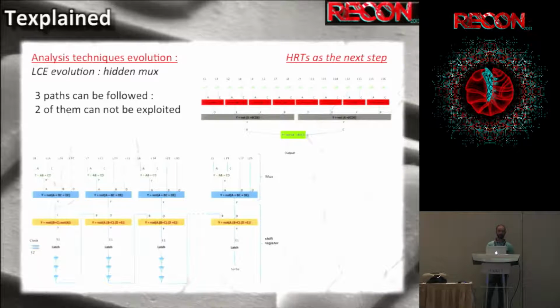The first pass was leading us to a situation with the 32 output lines ending with only 1 line. So for sure, it's not the good points, because it's not a 1-bit processor, it's an 8-bit processor. I want to find 8 registers where the data are in clear. This is my goal.